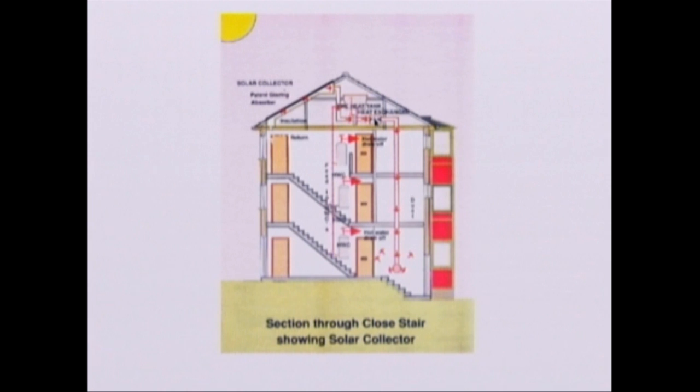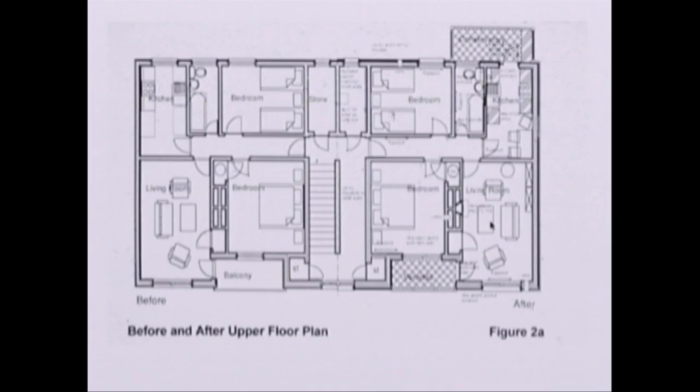So in other words, the Scottish regulated energy uses, can we get that down to zero carbon? Well, looking at the plan, the obvious things to tackle first of all are upgrading the wall to higher standards. That's relatively simple. All we need is more insulation on the outside. To get the windows to a higher standard, say a passive house standard, all we have to do is spend money and we can get a triple glazed window which will achieve an overall U value of 0.8.